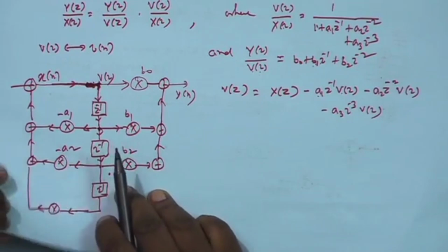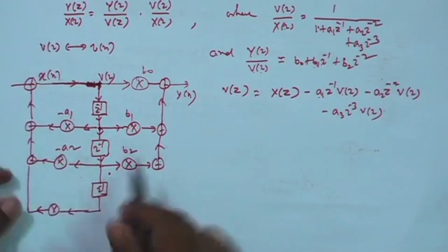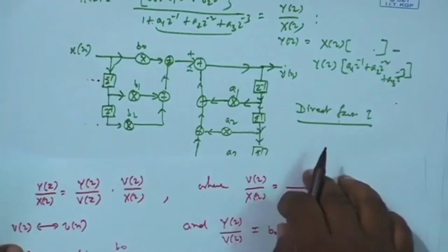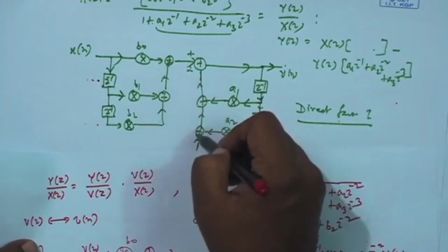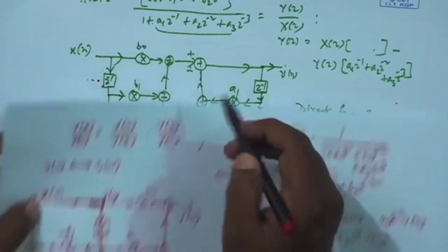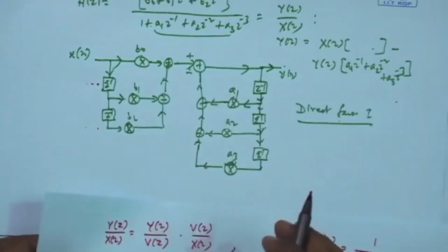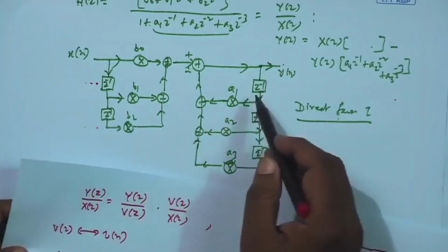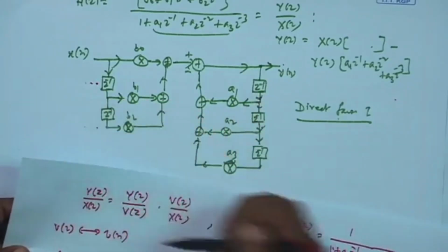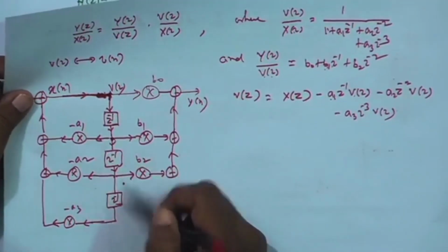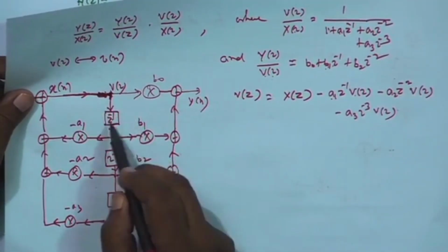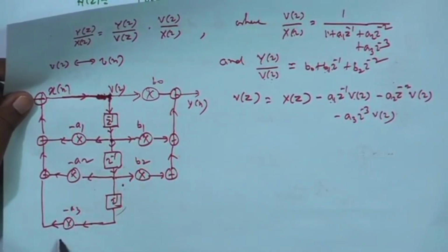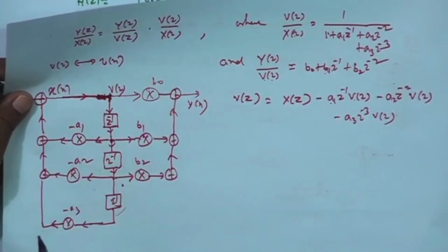Okay. If you now compare, you are having the same number of multipliers and adders. That is not a problem as compared to the previous structure. But here you have got adder, adder, and adder, adder, 3 adders. Okay. That I am not having. Delay is optimized here. How many delays? 3 on this side, 2 on this side. But now I am using only 3 delays. 3 delays is actually an array of D flip flops, because this is a bus. So, that is like a shift register, another shift register, another shift register. So, we require fewer delays here as compared to that.